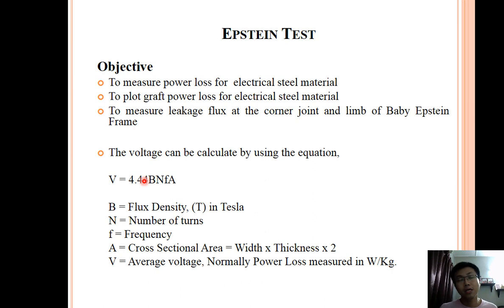In this subject, during your lab session, you will go through the Epstein test. The Epstein test is for us to measure the power loss of the electrical steel material, and then for us to plot power losses for electrical steel material, and also we can measure the leakage flux.